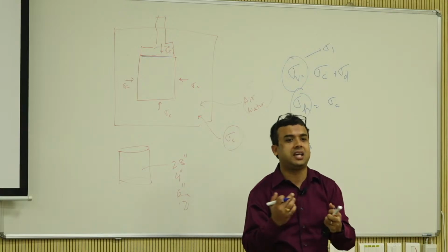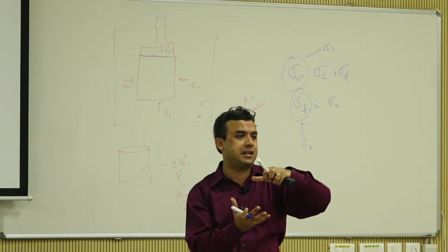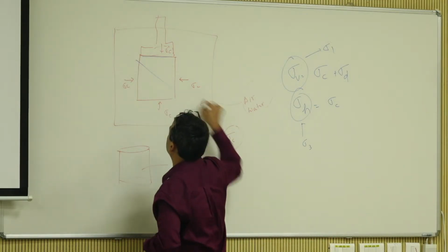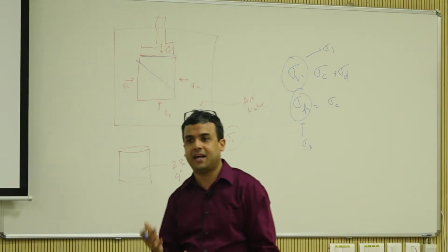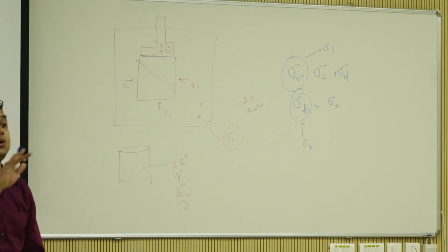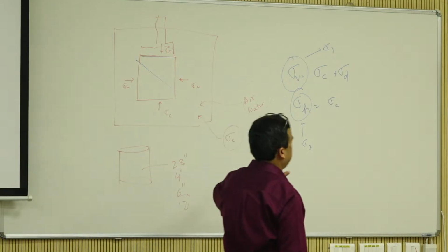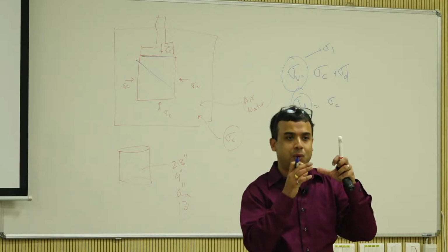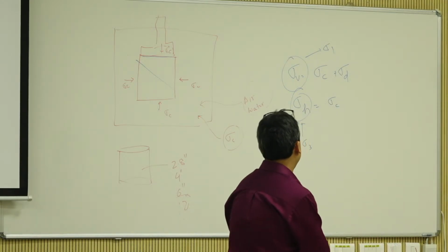So now you are going to apply the deviator stress at a given rate, and you are going to induce axial deformation in the specimen, and then at one point you're going to have some kind of a shear failure, right? Because soils and aggregates always fail in shear. Even if you induce compressive loading into these things, you are actually failing in shear. That is the reason you measure shear strength, right?